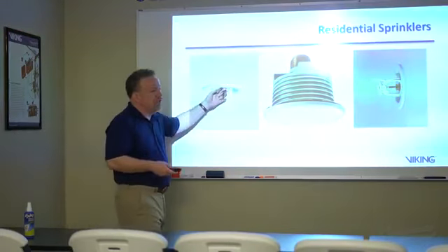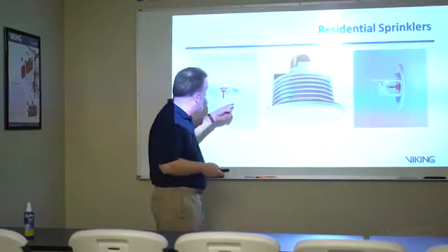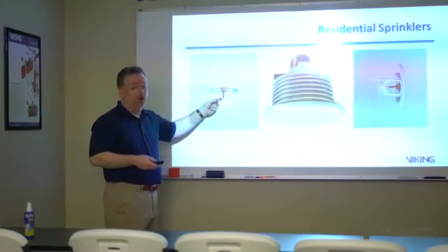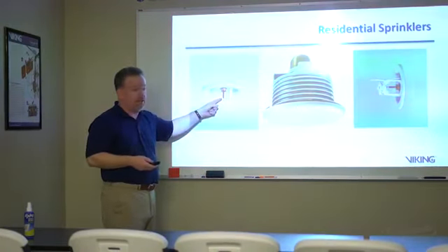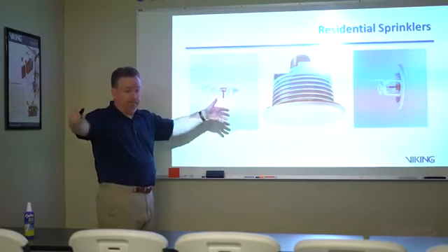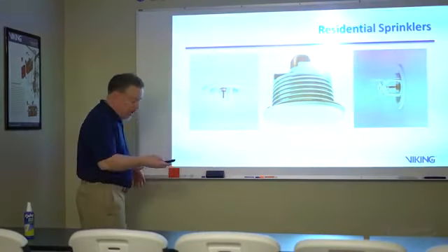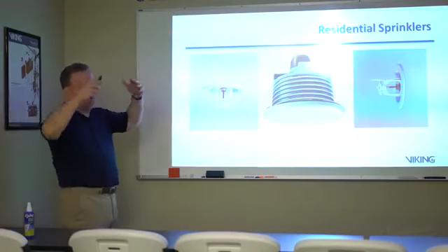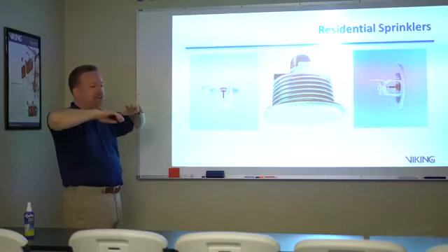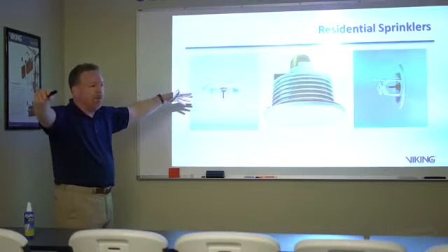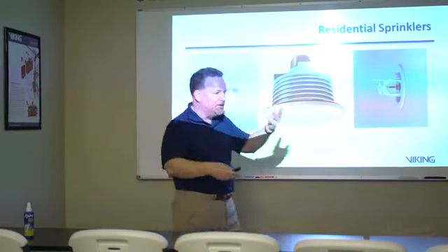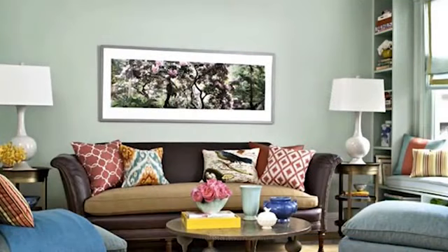So in order to do that, you had to have a sprinkler that was capable of quick response. You can see this characteristic right there. A broader spray pattern to cover a larger area, not necessarily because they needed that extended coverage, but if you take a look at a standard living space in a home, where's the fuel load? It's out along the wall in a living room.